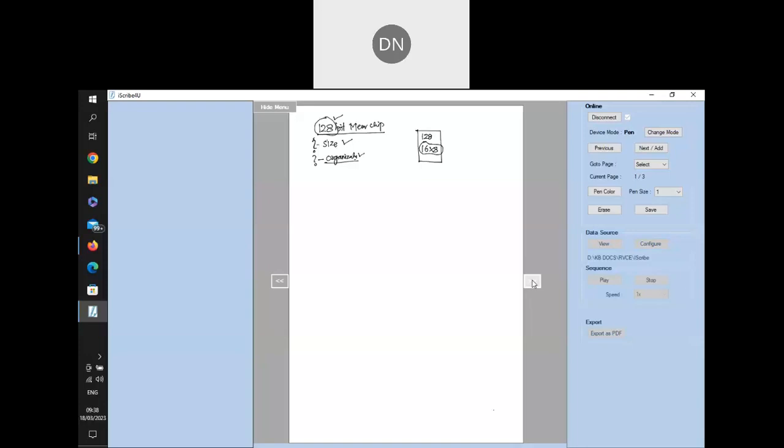The same 128 bits can be organized in a different way. It can be 32 rows, and the number of columns in a row can be different. It can be 64 rows and the number of columns can be less. It can be 128 rows and each column can be 1. Like that, a variety of combinations will come. That is why you have to purchase multiple memory chips to prepare one memory requirement. If I am building a computer with 1 mega into 32, I may require 1 mega into 1-bit chips, 32 chips. So you have to choose multiple memory chips to design a given memory requirement.